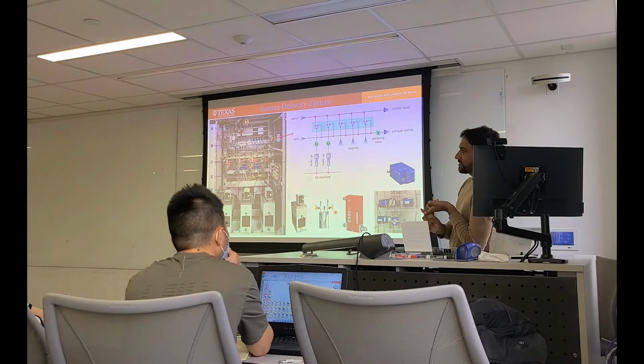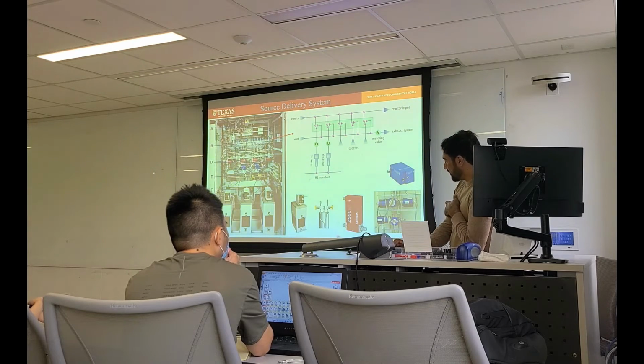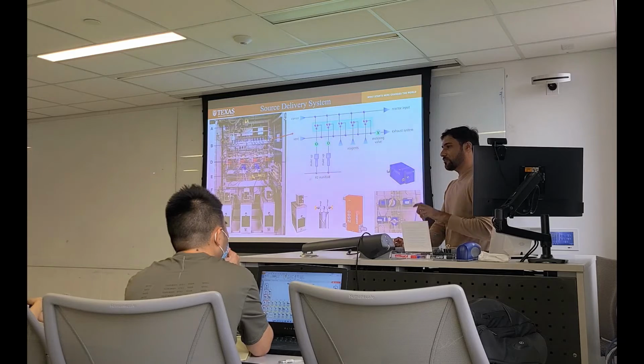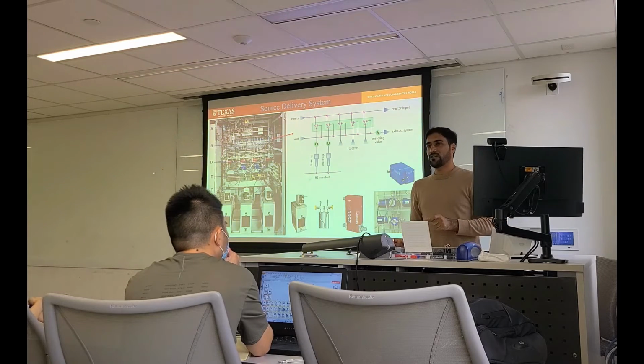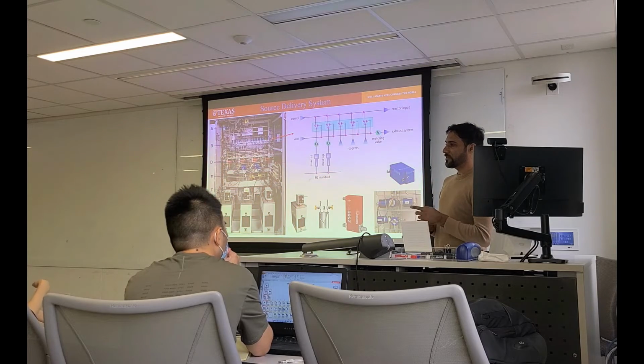So this is the confusion. In conventional systems, hydrogen and nitrogen are used as the carrier gas, and we cannot use both of them to carry the source. Suppose you are using hydrogen for gallium. Each MFC has different calibration factors. If you have an MFC specifically for hydrogen and then decide to use nitrogen, you should have a separate MFC for nitrogen because the calibration factor is different. Otherwise, you will not get the exact flow you want.